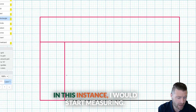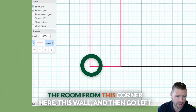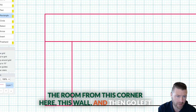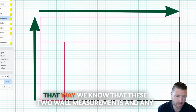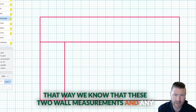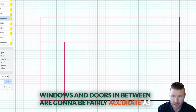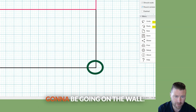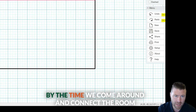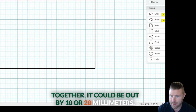In this instance, I would start measuring the room from this corner here, this wall, and then go left to right all the way across. That way we know that these two wall measurements and any windows and doors in between are going to be fairly accurate, as opposed to starting in this other corner where cabinets aren't going to be going on the wall. By the time we come around and connect the room together, it could be out by 10 or 20 millimeters.